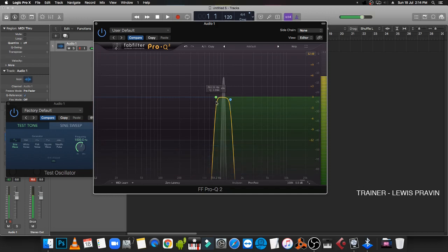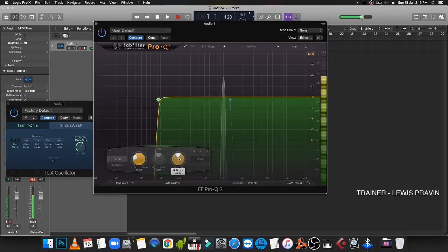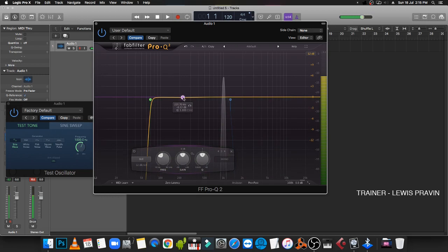Next important thing is, let me select this particular graph and switch it off. Now, if I select a particular frequency, you always get 3 knobs. So this knob is to dial in the frequency. This knob, for example, I'll click another node. This time let the node be right at 1000 Hertz. I could also key in the 1000 Hertz. So this is exact 1000 Hertz.